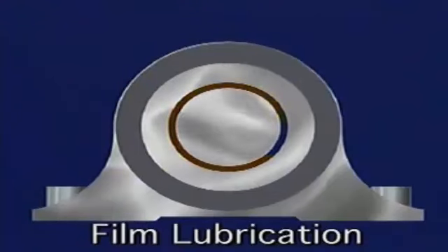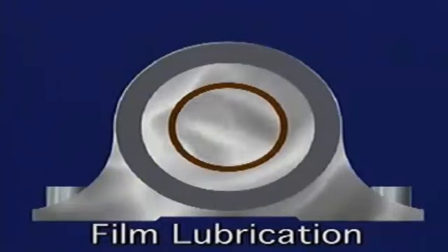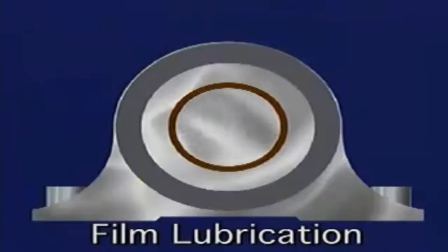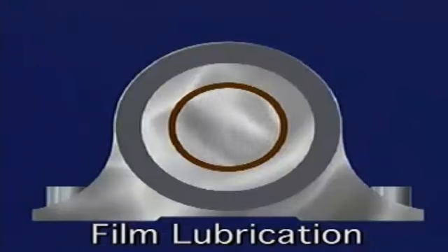Lubricant stored in the bearing housing is picked up by the spinning shaft and pulled between the surfaces of the bearing and the shaft, where it forms a film. As the shaft rotates, it floats on this film of lubricant, so there is no metal-to-metal contact between the shaft and the bearing. If the film of lubricant were not present, the shaft and the bearing would contact each other and wear out rapidly. The film of lubricant also increases the amount of load that the bearing is able to support, because it distributes the load over a greater area of the bearing surface.